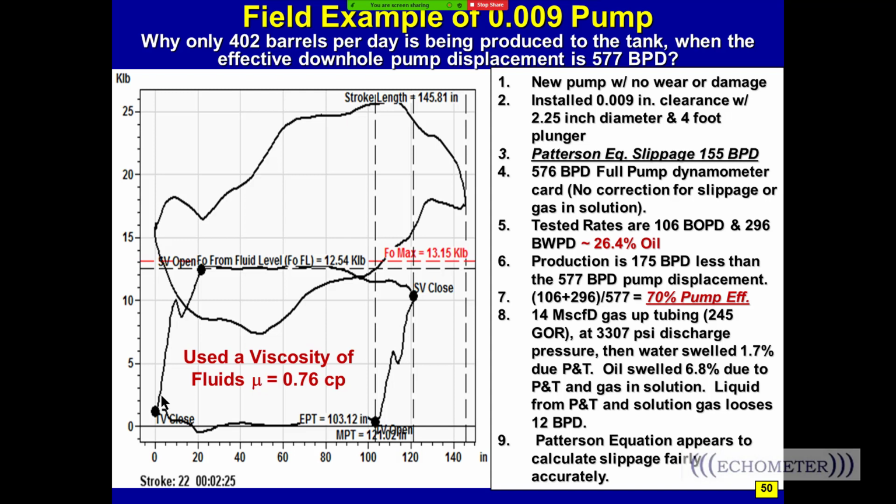But that's a great question. This was an argument that Sam Gibbs and Ken Null and I had a lot, because at first I thought this was indicating unanchored tubing, and Sam and Ken said no, this is just slippage. And after I saw this data on this well, I said, hey, this well is anchored because the operator actually pulled tension on the tubing, and this is only slippage. And when I agreed with Sam and Ken about this, they said no, the test well at Texas Tech is unanchored, and I said no, it's anchored because that slope is just due to slippage.